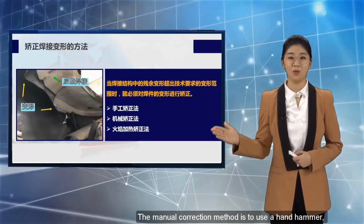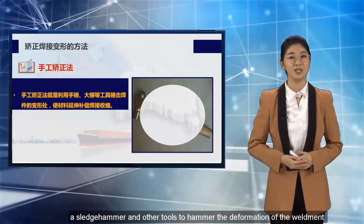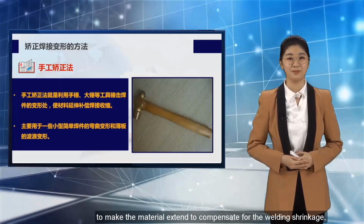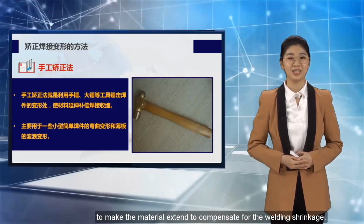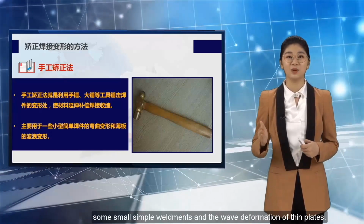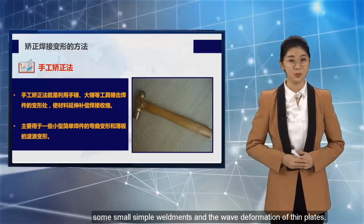The manual correction method is to use a hand hammer, a sledgehammer and other tools to hammer the deformation of the weldment to make the material extend to compensate for the welding shrinkage. It is mainly used for the bending deformation of some small simple weldments and the wave deformation of thin plates.